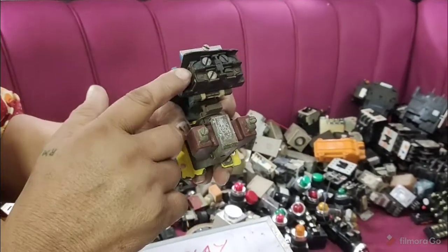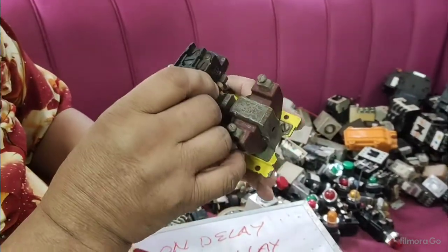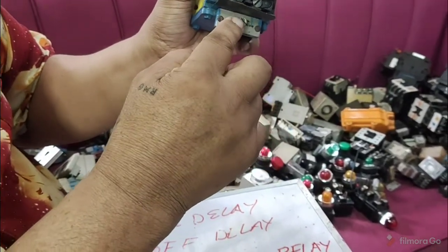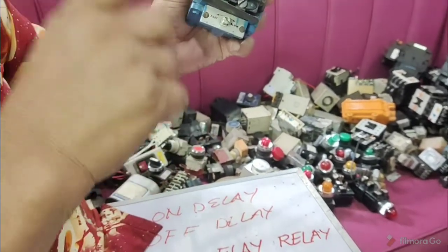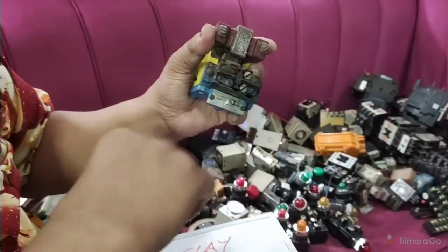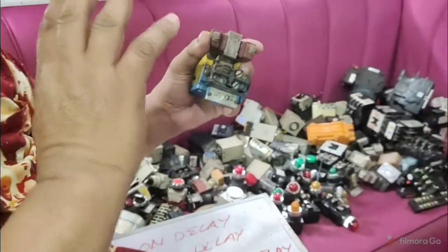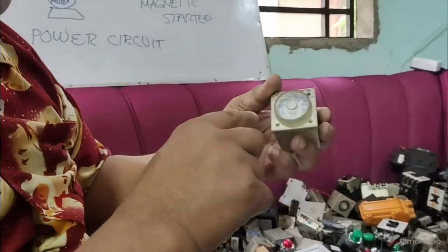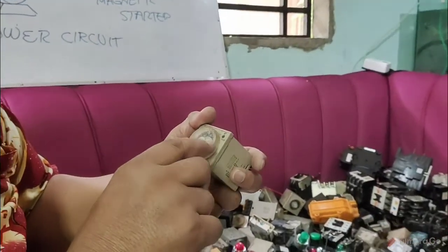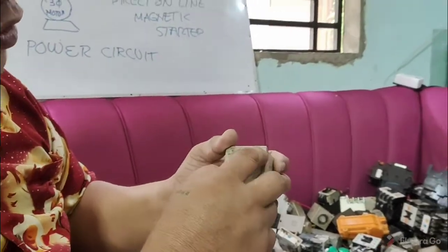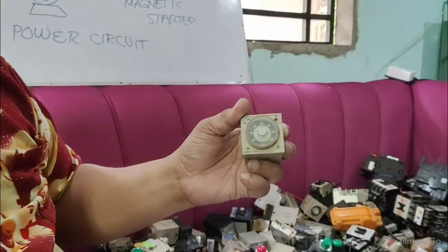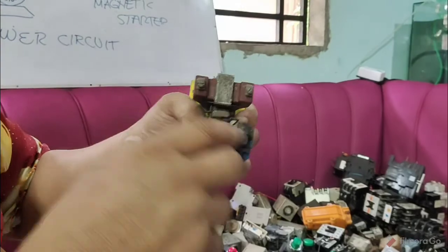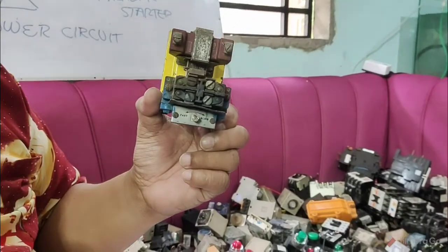So if you want to adjust the timer, whether you want it to become fast or slow, you just adjust this screw. But of course, let us say you need only 60 seconds, so adjust it, then time it, while it will click, so 60. Not like this one, you have already done indicating here. You have here 2, 4, 6, 8, 10. So if you want 10 minutes, you adjust immediately to 10 minutes. Very easy. But this one, you need to time it. Then adjust, then time. So this is what we call a pneumatic timer.